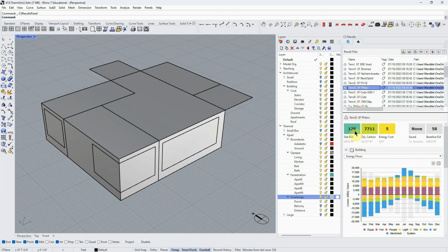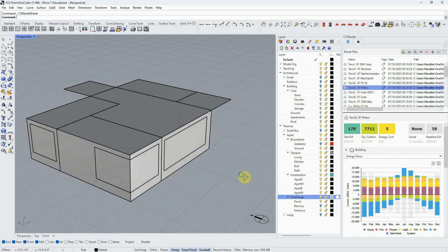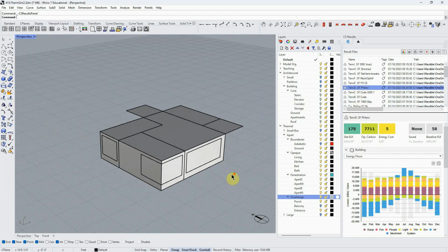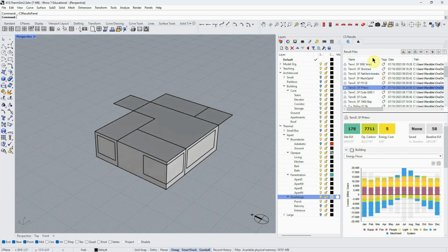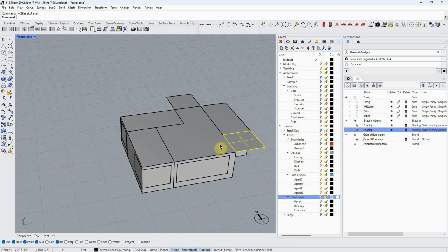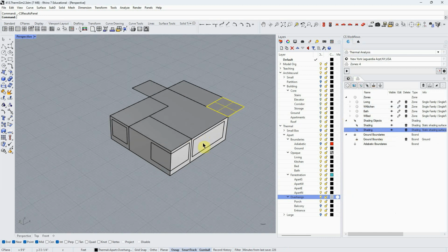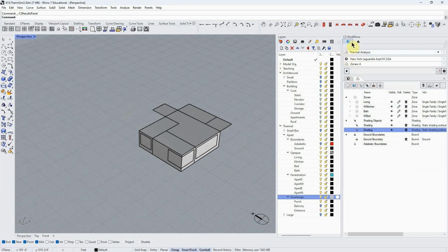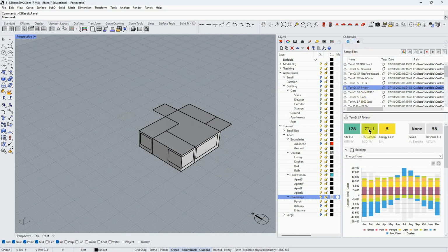The opaque envelope. Now remember too, this is a lot of glazing. We're not looking at changing that. We're not looking at shading it. Though we actually do in this model right now, we have shading on. But we don't have any shading over this expansive southern glass. So there's lots of things we could do. We're not designing here. We're learning the workflow.